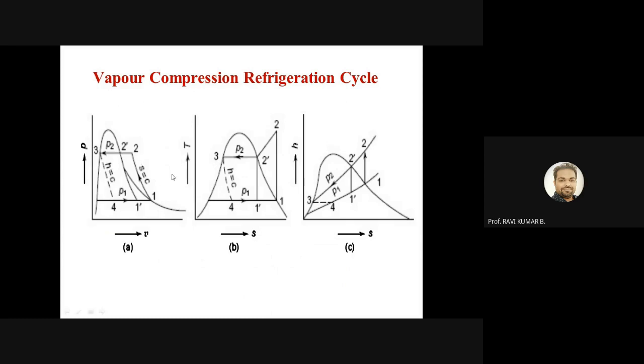After that, our main motive is that we have got the highest possible pressure of the cycle, which is basically required. After that, the condenser will reduce the temperature. The condenser will take away the heat and cool the vapors from the two-phase stage to reconvert them back to the liquid form. It is a superheated vapor, so it is getting cooled from 2 to 3, and finally you reach just at the saturated liquid line. So the final state is saturated liquid.